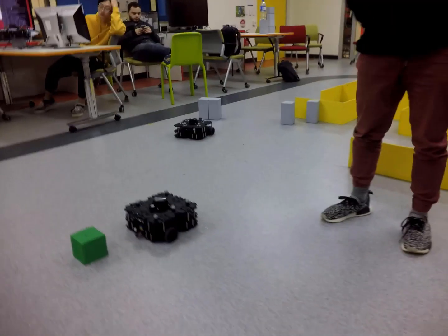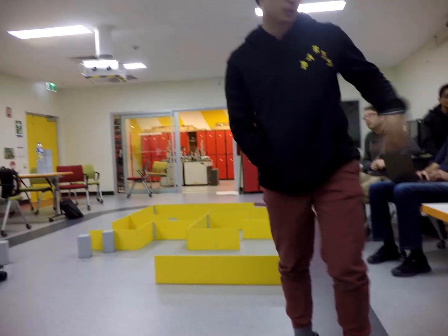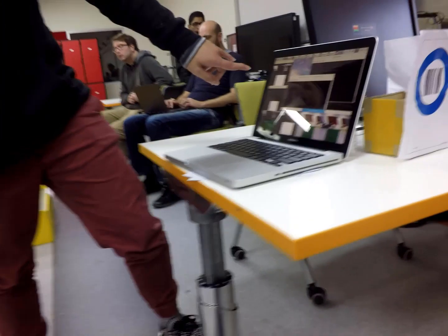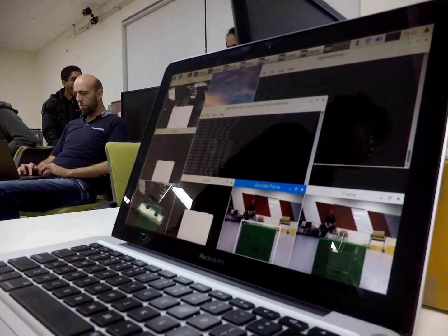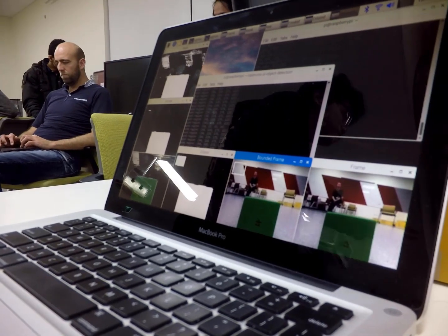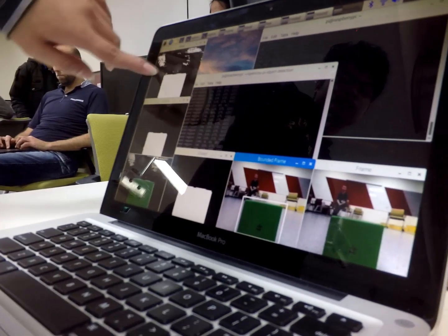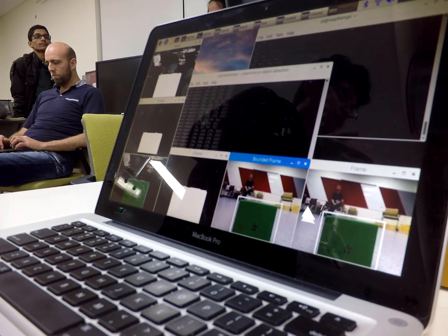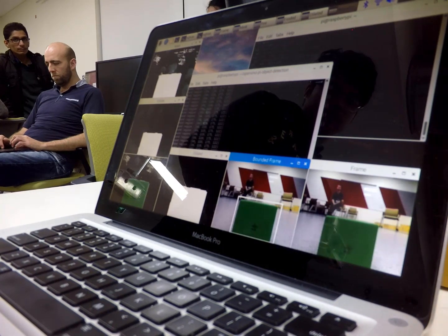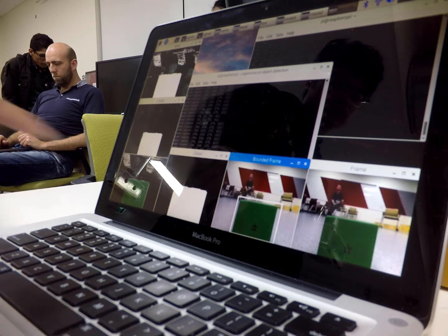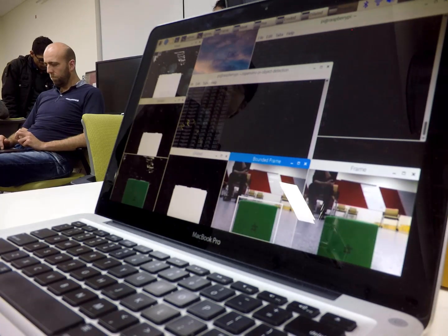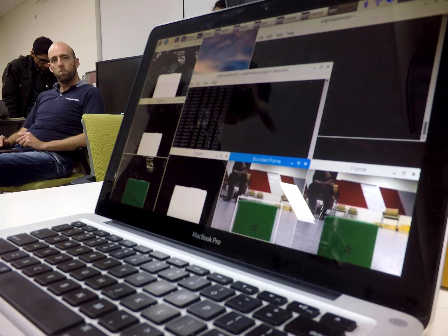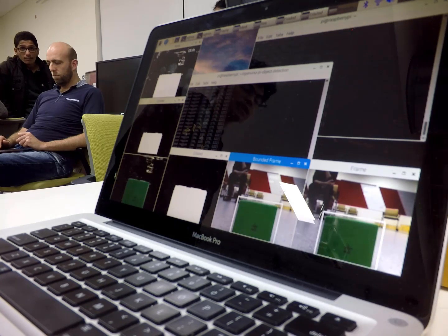So I went from that to color thresholding, so I can detect the block, as you can see here. I used HSV to detect the green from the rest of the image. Since there's still noise, I had to erode the noise and then dilate it back to its original size. Then I bound the box data to the ROS, which would translate it from a string into an array.